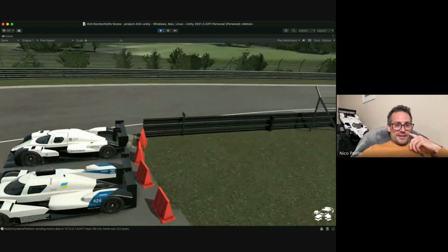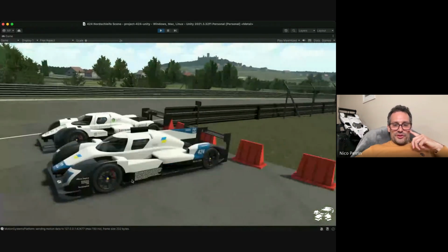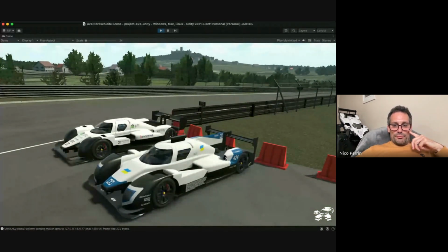And then you've got things like, you see this triangulated fence at the exit of the front wing air. That will create pressure again on top of the floor. That fence is very small on the Le Mans car, just to allow the air to come out without creating that pressure.